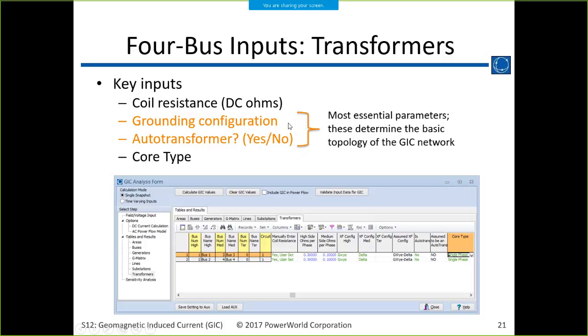Question on that, Scott? Yes. That would be a tertiary that would run out and plug into something, not a stabilizing line, right? We don't need to do anything with that. Right. Well, really any tertiaries, we're generally going to assume that they're delta connected. But there are some that might exist in the field but don't exist in the model. Like a tertiary we use for, we call them stabilizing lines, but we don't bring them out. Right. So then we just ignore that. You can ignore that, yeah.